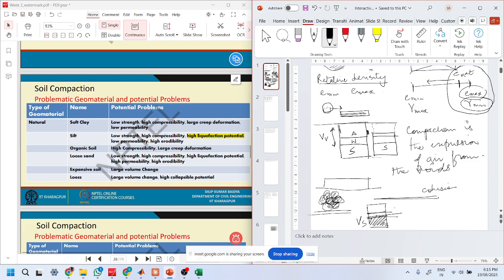You know, if you take mostly sandy material, you take it in your hand, it will fall. The same thing will not happen with clay because clay has inherent cohesion. Sand does not have that. And because of that, due to forces of nature like wind or water or anything, sands get very easily eroded.